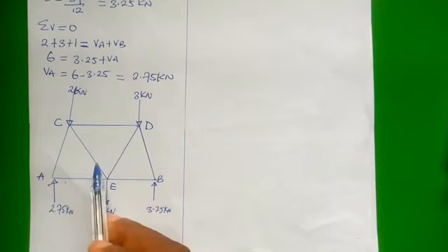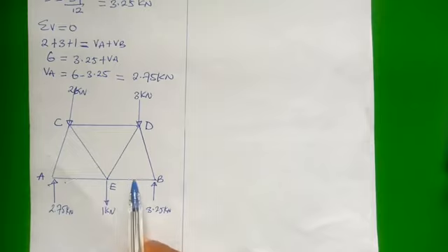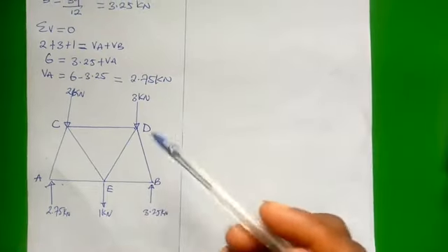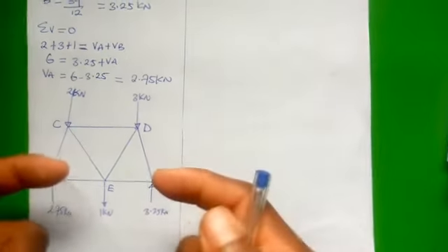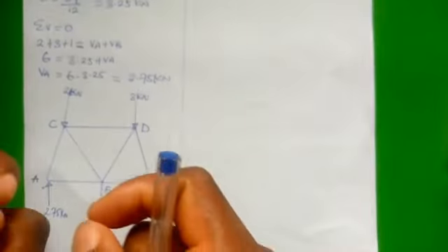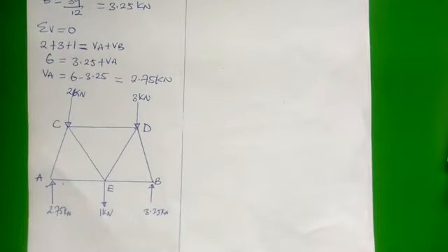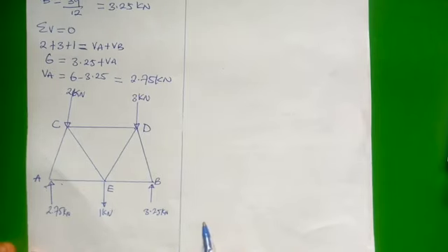you can decide to assign either compression or tension to any of the members. And you know, when you talk about compression, it's just the force trying to bring two things together. And what we're going to represent here is the internal force, which tries to oppose the compression. Likewise to tension. But for easier understanding, let's assign compression to all the members. In that case, if any comes out negative after calculation, we will know it is tension and not compression.